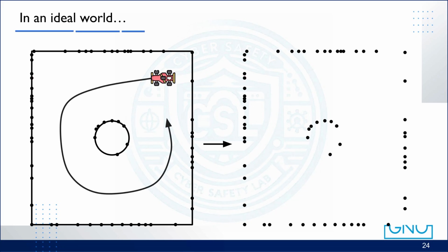After some time, the accumulated scans begin to reveal the shape of the environment as a sparse point cloud. It's not a full map yet, but the outlines of walls and obstacles gradually become recognizable. In this example, the measurements look sparse, but if the robot continues driving and collecting more scans, the points become denser and converge into a realistic representation of the environment. Under perfect odometry and perfect sensing, SLAM essentially reduces to stacking more and more scans until the map becomes complete.